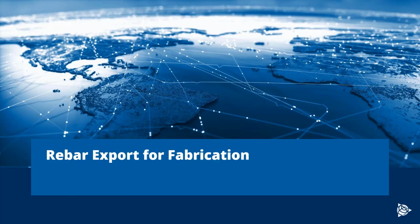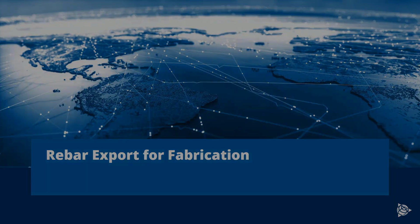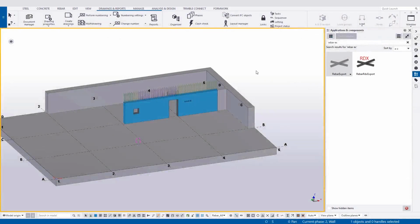Now, we also have the ability to add more to that and make our life and the fabricator's life easier. We can export our rebar based off of the model geometry directly to bending machine formats in either ASA or Soule format. Let's go ahead and take a quick look at how we could accomplish that.